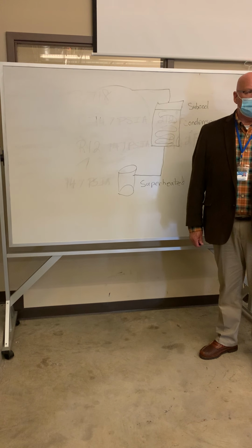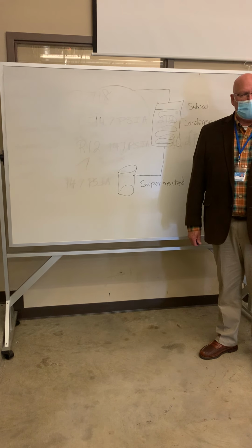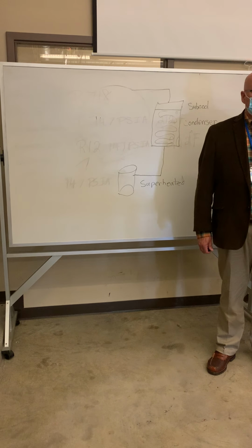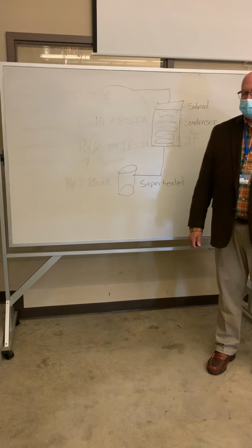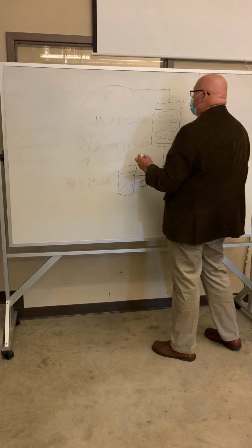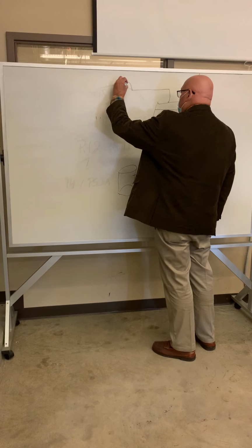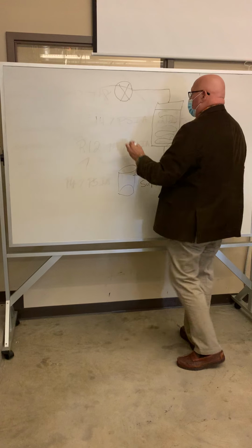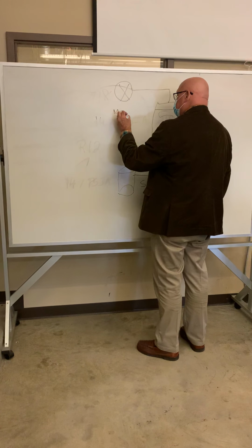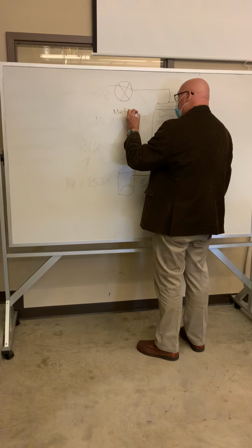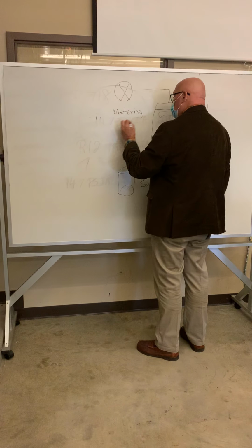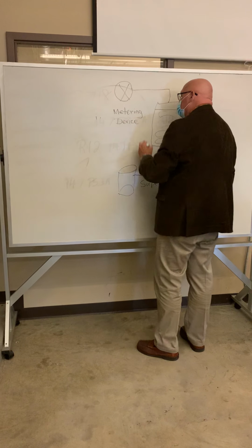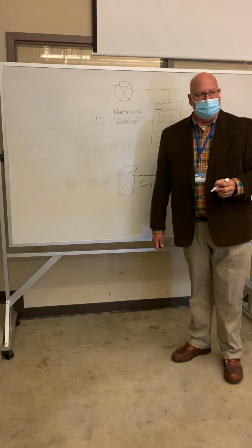We call that the liquid line because it's required for a unit to work correctly that the liquid line is a solid column of liquid refrigerant. It travels to another one of those devices, distinguished with a circle and an X. And this is called the metering device.